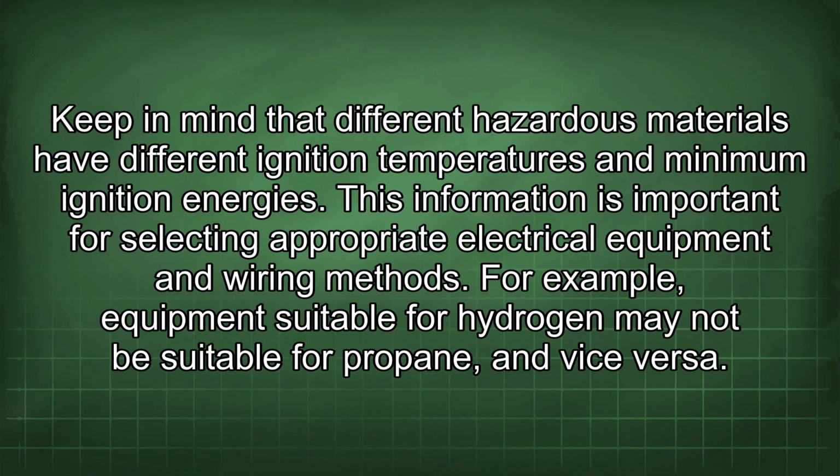Keep in mind that different hazardous materials have different ignition temperatures and minimum ignition energies. This information is important for selecting appropriate electrical equipment and wiring methods. For example, equipment suitable for hydrogen may not be suitable for propane, and vice versa.